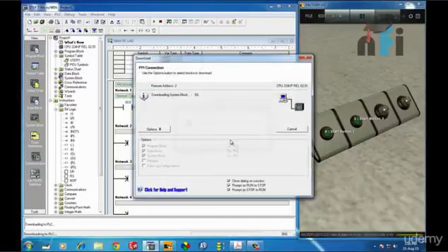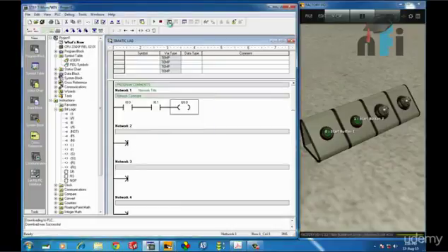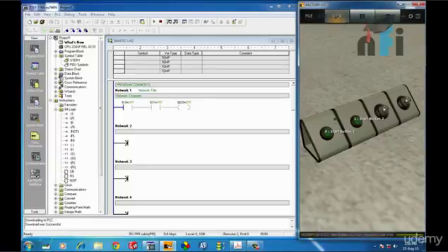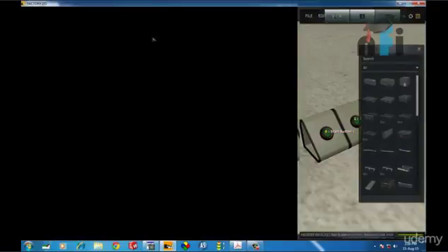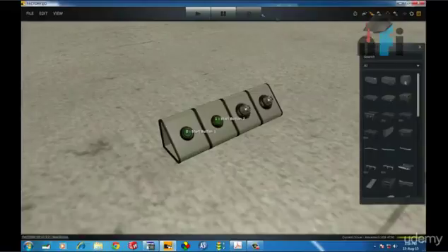So download this logic in the PLC and let's see the results. Click download and let the program transfer. Once it's downloaded, it will ask me to place the PLC in run mode. So I'll click OK. Then I'll go to program status and I'll click on run here. Now when I press this button, it will retain the state, but this doesn't go on. Let me check the logic. Maybe I need to link that again. Yeah, the buttons are not linked here. So I have to link the buttons to my PLC. Now it makes sense.